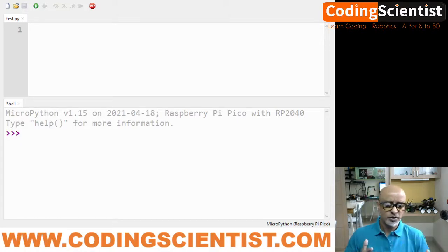The way to connect your board to the external world and control other components and features is through the GPIO pins only. Hence, the pins are available in the machine module. And what is that module? It's a library, and that is machine.Pin. Okay, so we need to make sure that we import that first, and then we create the pin which is associated with your Pico's pin numbers.